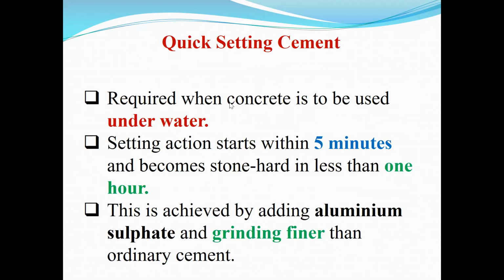Okay, we have got another cement, the quick setting cement. It's required when concrete is to be used under water, because when you use concrete under water, setting action starts within 5 minutes. Normally, we take that it should be 30 minutes or 60 minutes like that. But here, within 5 minutes, setting action takes place, and within 1 hour, it becomes hard like stone. So how is that achieved?